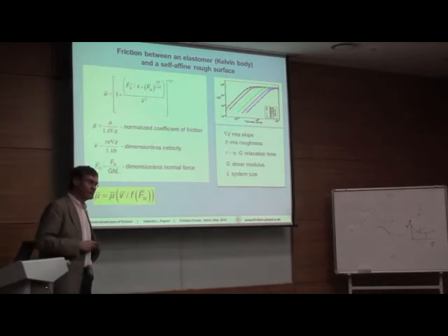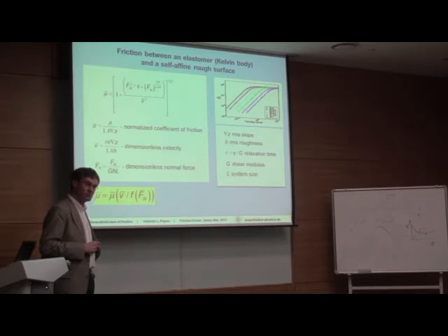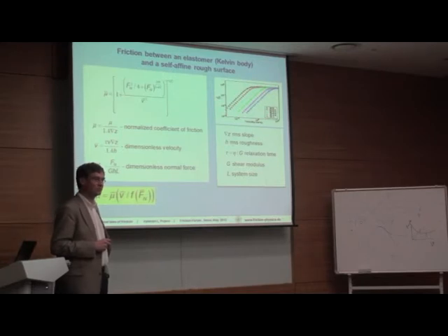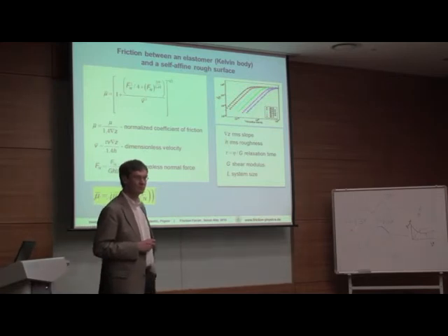So you stretch it, you release it, and those asperities, continuously vibrating, give a very high frequency. I think I said once that all noise starts with a very high frequency, in excess of 50,000 hertz, and then comes down into something that's audible. We never realise that, because we generally record at 20,000 hertz and never up to 50 or 100,000 hertz. If we did, we might see the whole system vibrating at these very high frequencies that cascade down to an audible frequency.